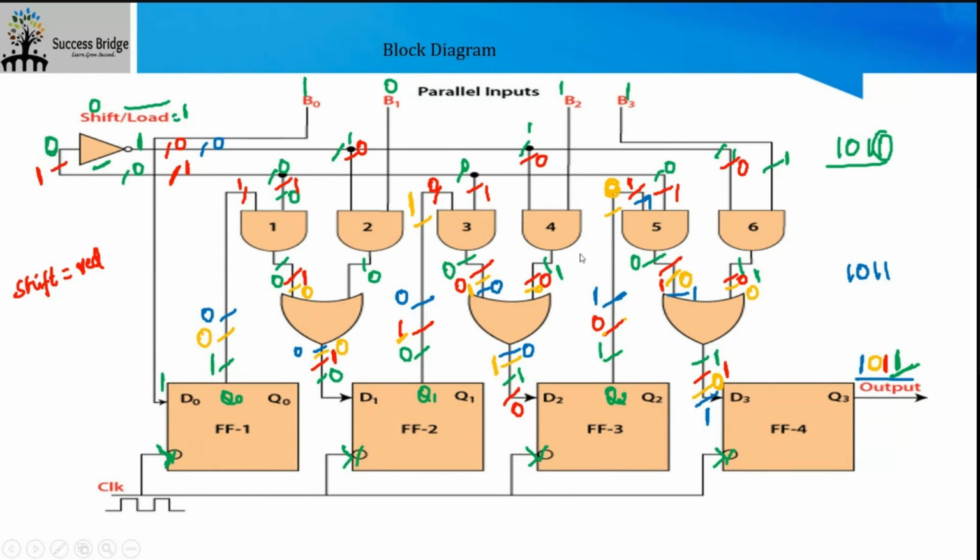Because this is a complex functionality which represents muxing. But we will have mux here already. So I'll explain that in DFT scan architecture. This structure is only possible and implemented in RTL designs. But in DFT, we don't use this architecture because each flop has internally one mux that is called scan mux, which we will discuss in DFT. So we don't need this architecture.